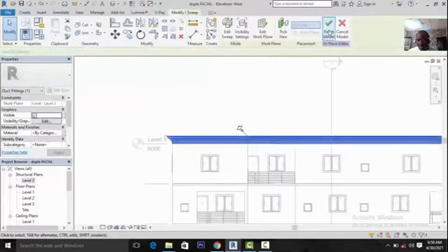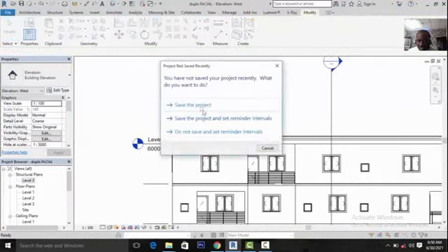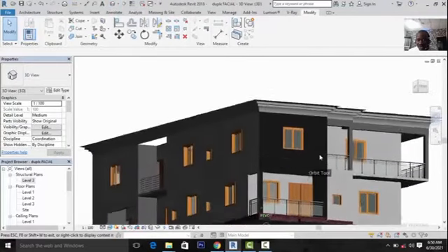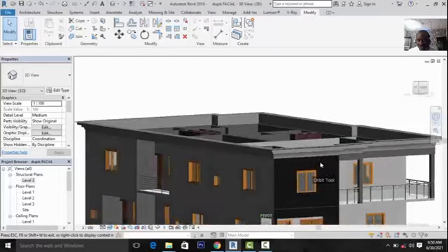Now if you then click on finish, you can see the shape gotten. So folks, it's as easy as that. I don't want to save it, so this is what I have. So that's how to create a concrete fascia. Then you can now add your roof on top of it.